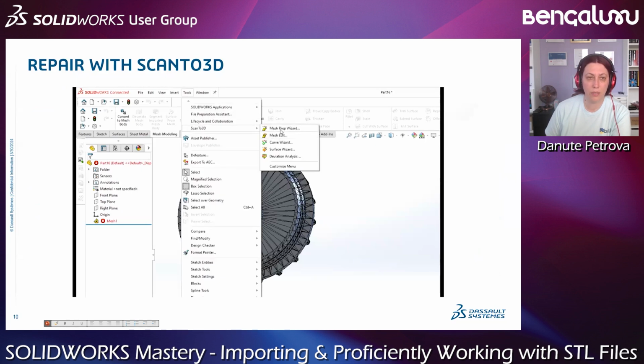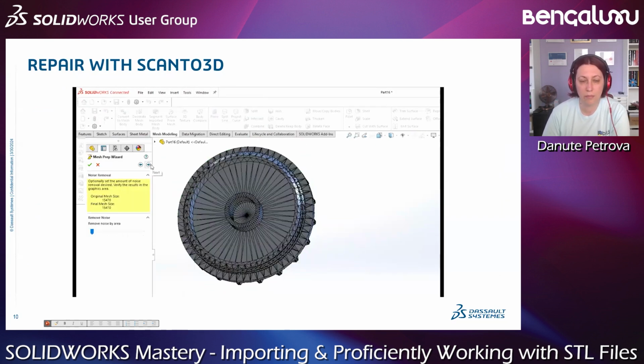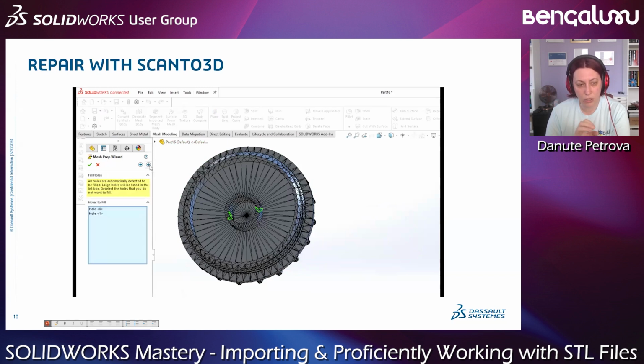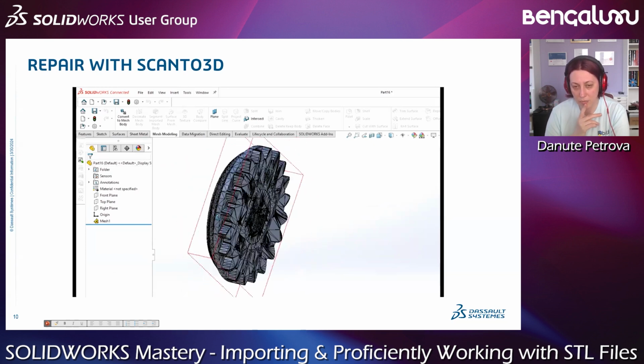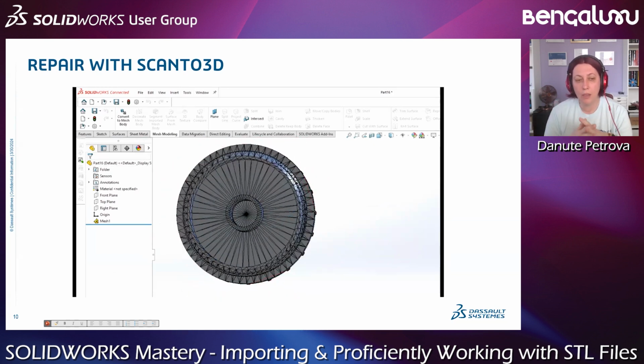So this is a video that will show you how to repair with Scan to 3D. Here it's showing that there is some error in the faces. What I did is just reduce the size of the faces by 1, and it showed the 2 holes. If you go to the next step without changing anything, it will not repair your model.